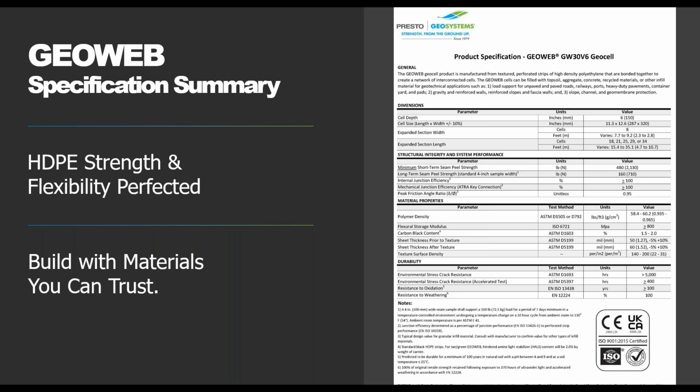We add carbon black to the material for UV degradation. If it's our walls, which I'll show you some pictures of in some slides, we add a high HALS content. If it's subjected to UV for walls and it's a colored geocell.